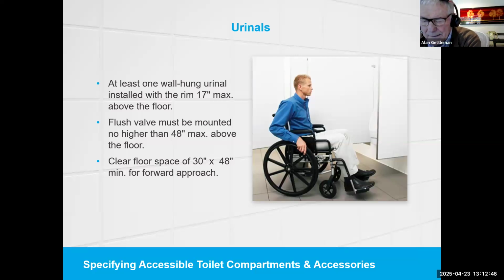Number one, we have had many issues with the AHJ and building inspectors who have seen that the grab bar in front of the accessory has a reduced wall clearance. There may be 1.5 inch wall clearance on the side of the accessory, but in front of the unit, the face of the unit may protrude 3/16 of an inch into the 1.5 inch space.